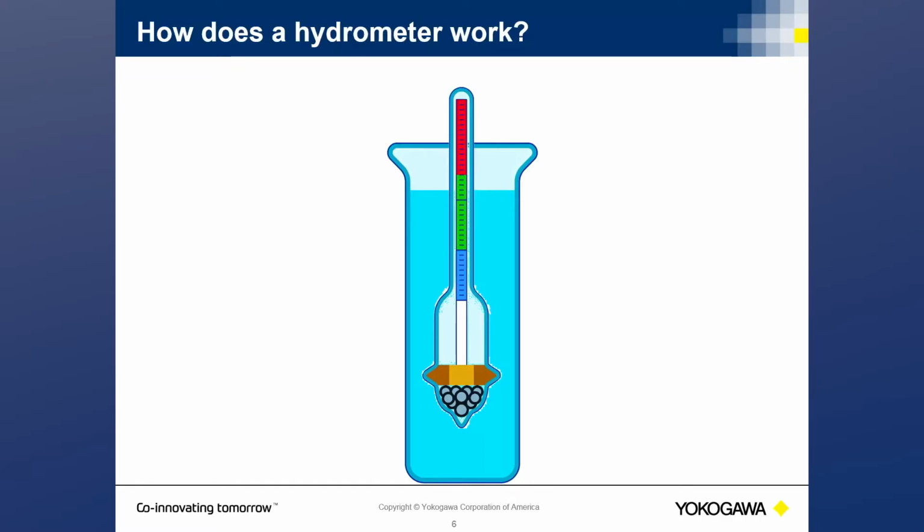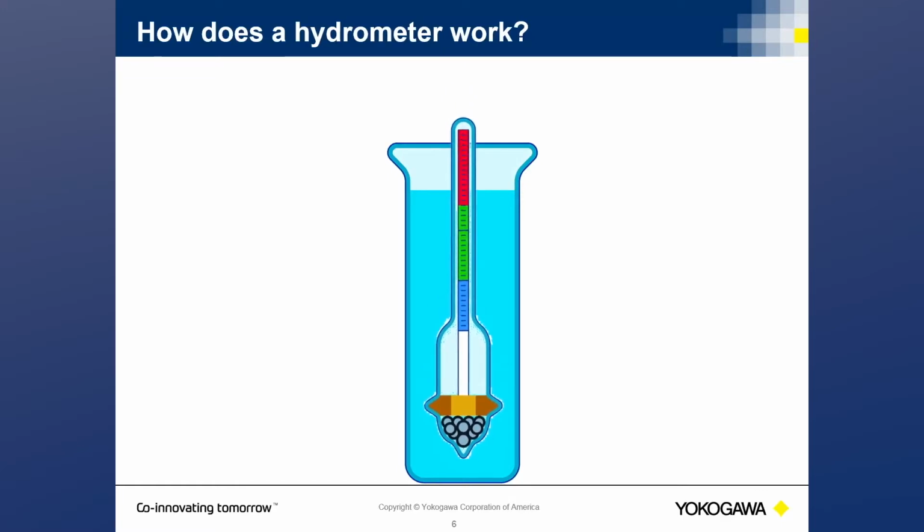The test cylinder has to be level so the hydrometer cannot touch the sides. Once you've done that, you gently press the hydrometer down a little more than the reading will be and allow it to float back up and settle out on its own. Then the reading can be taken at the point where the hydrometer stem floats in the liquid itself.